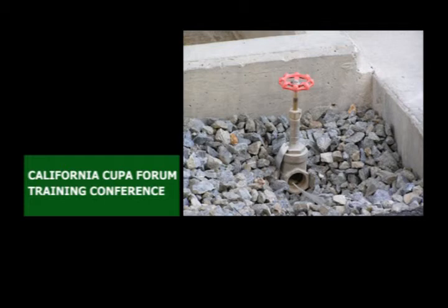But the only problem with this is operational. Can you drive by, tell if this thing is open? Not usually, no. You have to get out of the cart, walk over, take a look at it. Over time, it's going to be kind of a hassle to do the inspection, therefore, less likely it's going to get done correctly. What if that valve gets silted up? Maybe you can't shut it all the way, but you're still turning the handle, and all of a sudden the handle stops. Okay, it's shut, and it's not. But it's okay to use these.